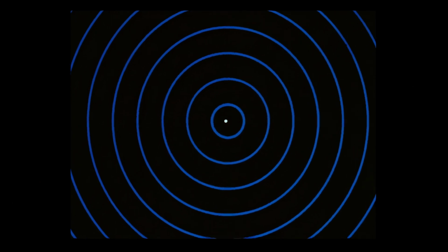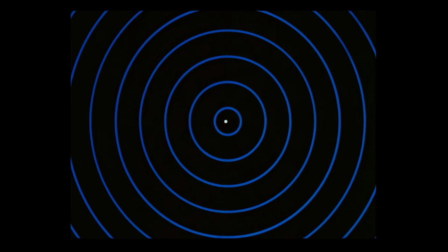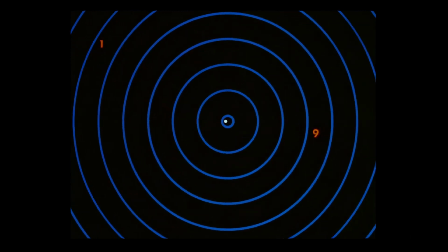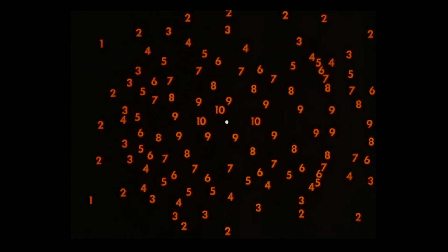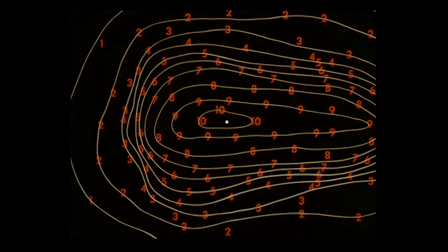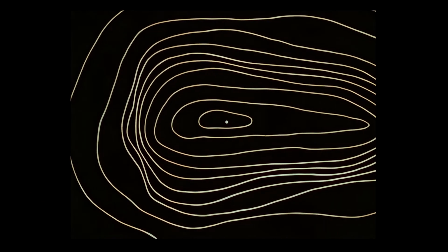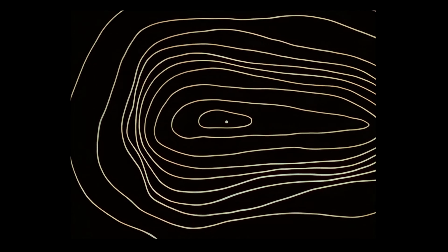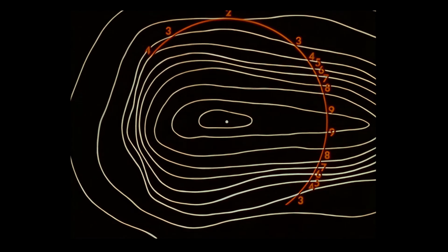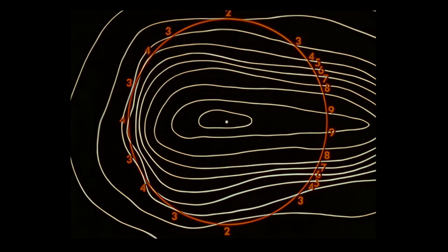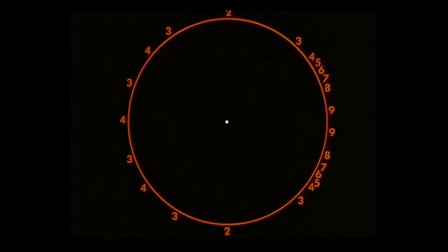Let us now see how we record the intensity of the energy radiating from an antenna. First, we sample the signal strength at various points. Such a record is geographical, and we can join the points of equal intensity to obtain contour lines. It is often more useful to know the shape of the field radiated by the antenna. To achieve this, we obtain field strengths at a fixed radius from the antenna. We now use a vectorial presentation to give each reading a magnitude and direction.